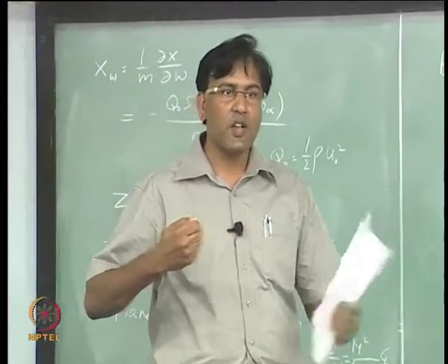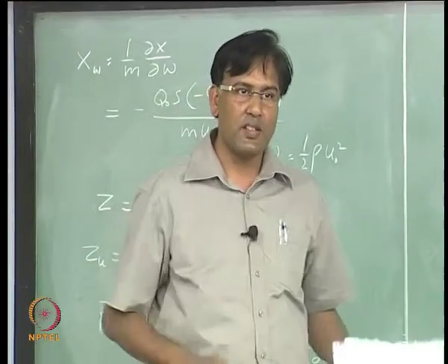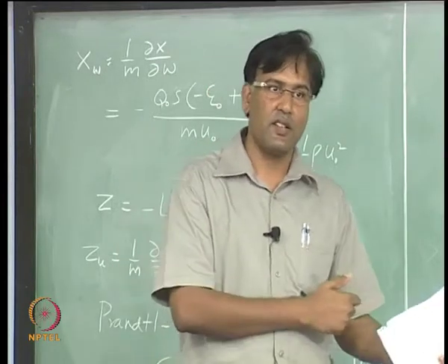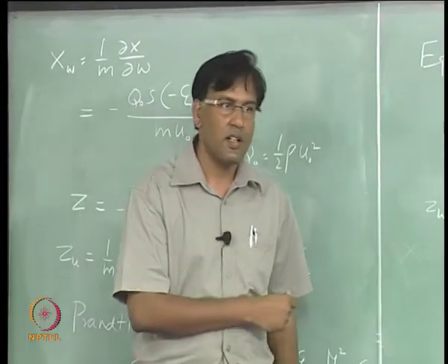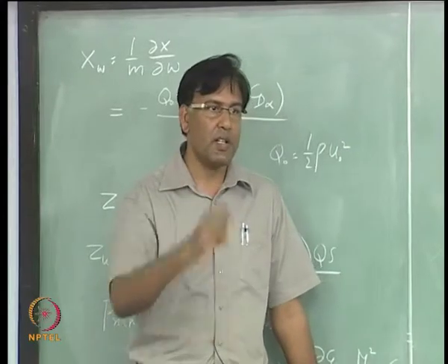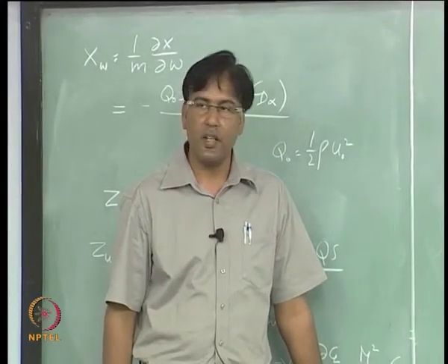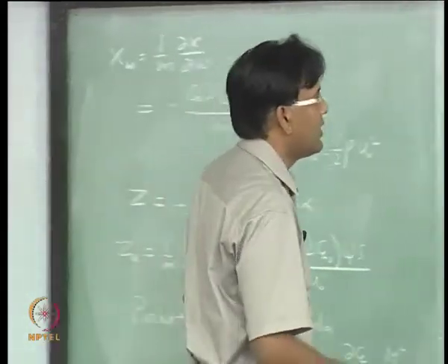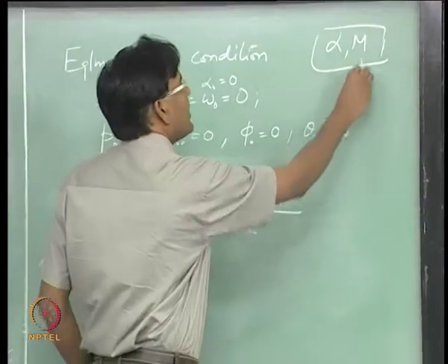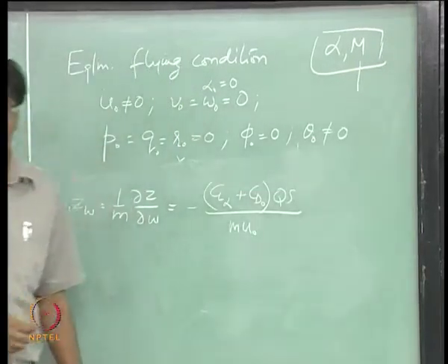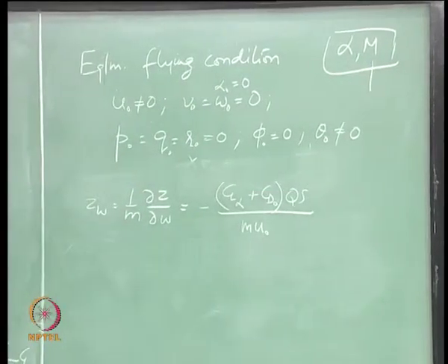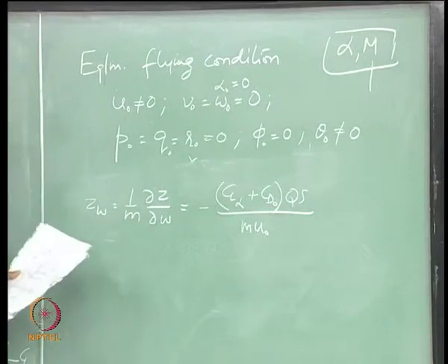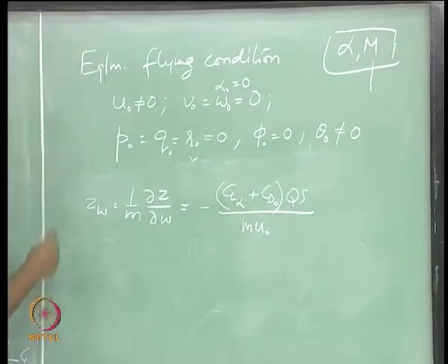At supersonic speeds you cannot actually change alpha the way you can change it in the subsonic speeds, because it will have large momentum in the forward direction if it is flying at supersonic speeds. So, there these derivatives with respect to Mach number will become important, and you can keep low alpha flights.